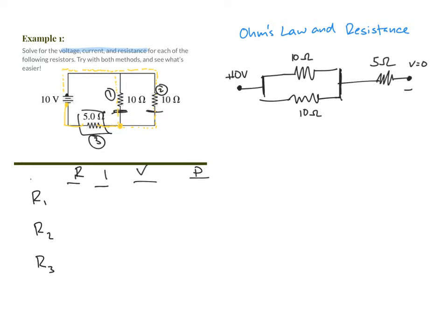To evaluate this, we first start by taking this big circuit over here and we're going to condense it down. We're going to take all those resistors and come up with their equivalent resistances. To do that, we're going to work with series and parallel circuits. You see that right here, I'm going to highlight this new part in red. This is a parallel circuit.